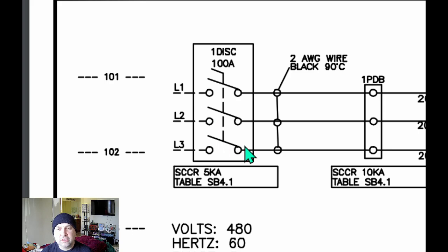So this is what it looks like in schematic form, and you're going to want to pay attention to that, because that's a lot of times where you're going to start on a piece of equipment. You always want to check your supply mains voltage and make sure that everything there is in working order and that you don't have any voltage drops across any of these legs.